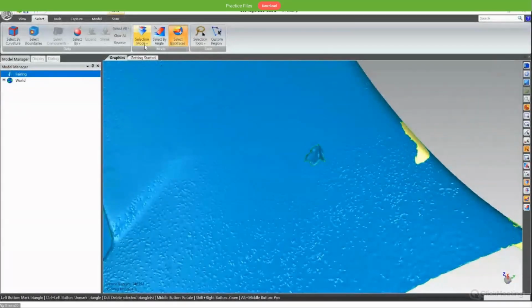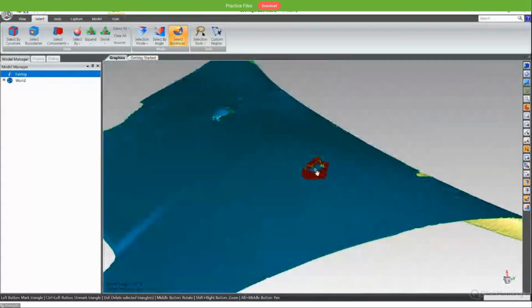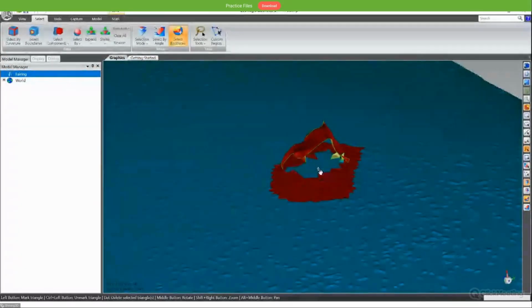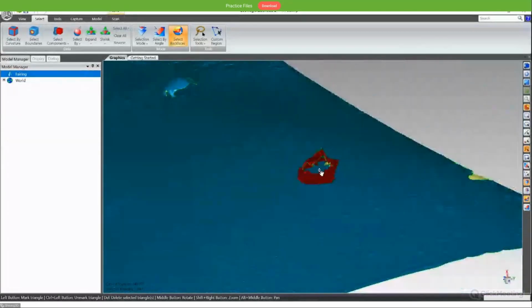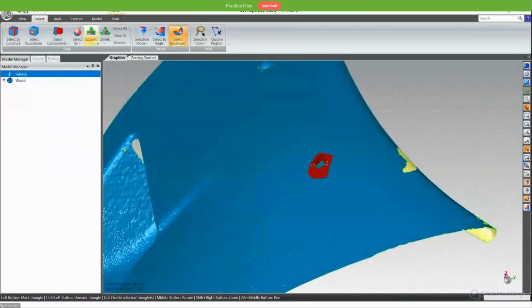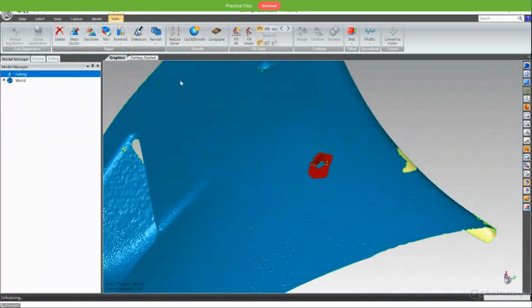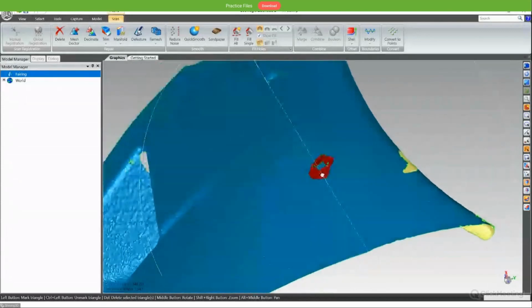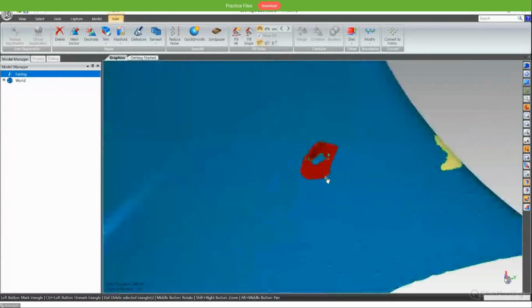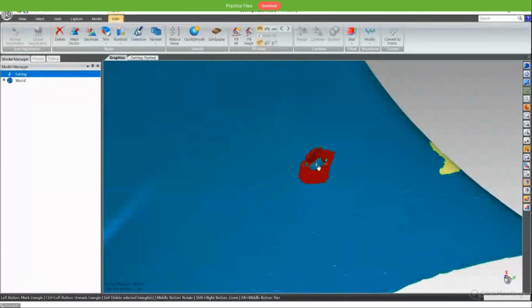If we only choose select visible only, you will find some part of the area hasn't been selected. In this case, if you run the defeature, the software will warn you that some regions could not be defeatured. And you click OK, you find it still exists.